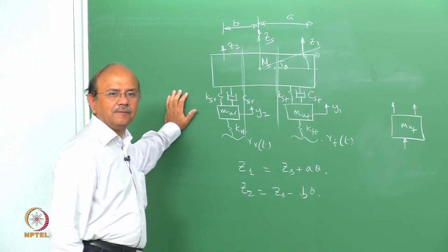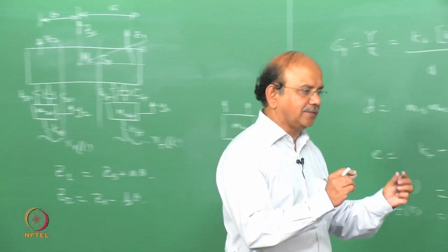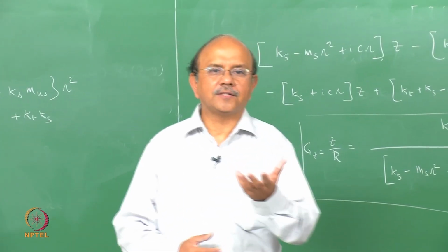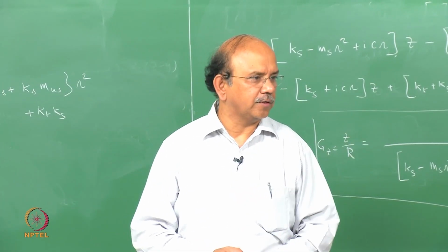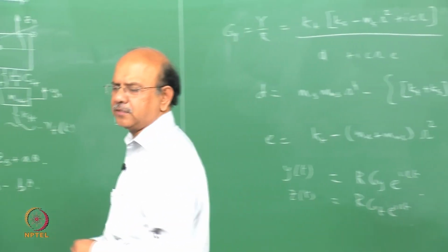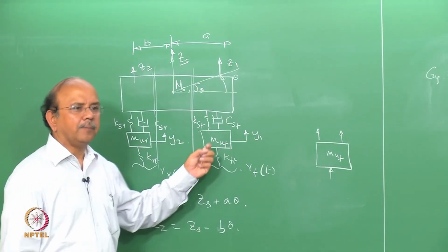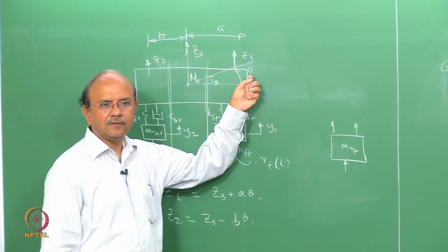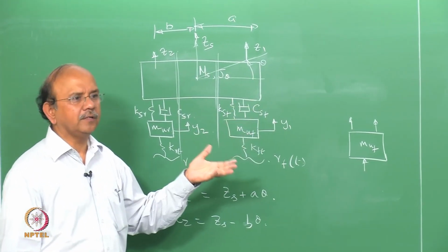First question. So what are those things that you have as an equipment, as a sensor, in order to do an experiment? You have an accelerometer, right? Okay, very good. All of you have used accelerometers. So the first thing you would do is, yes, I have an accelerometer, a data acquisition system, right? So what do I do? I put an accelerometer here, and I put an accelerometer here, and then start recording the